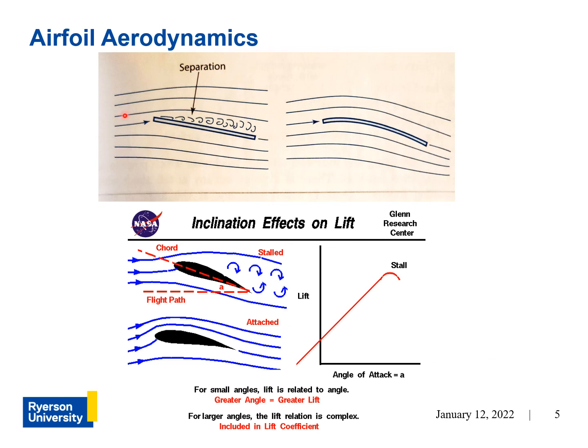Okay, so I just explained that the angle of attack of an airfoil and or its camber is the main reason why an airfoil is able to produce lift, and it does that by changing the flow of air around the airfoil.